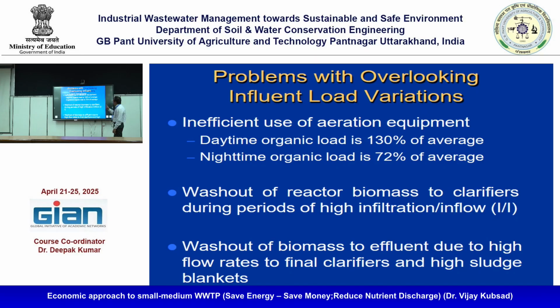Problems with overlooking influent loading variation are important. You have to think in a slightly different way. Earlier, the thinking was that overloading should not be there, and that was where you stopped. Now you are going a little bit further: you will see the concentration of MLSS and MLVSS, and at the oxidation pond, what the bacterial growth is.